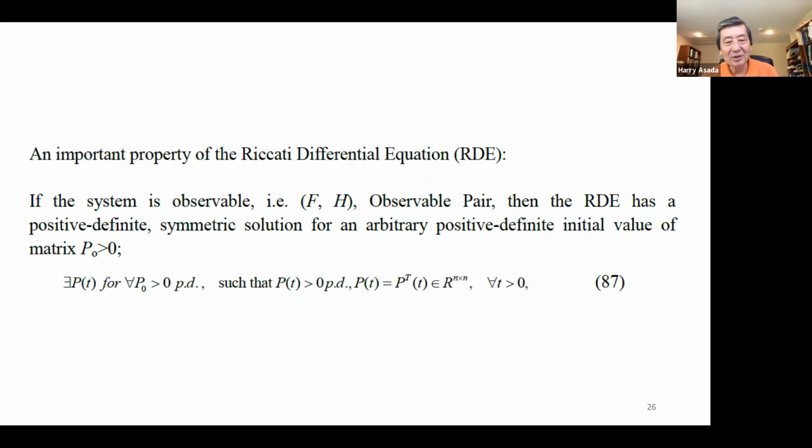And more importantly, the positive definite, symmetric solution is unique, and that's the only solution that we can use. So this is more theoretical, but all this analysis comes from that matrix fraction decomposition, the technique we used to convert the original Riccati differential equation to a linear differential equation. That's a tool.